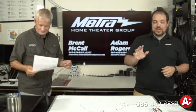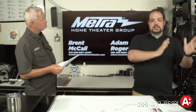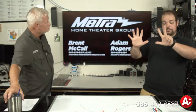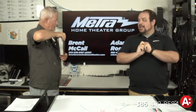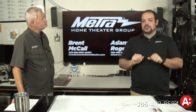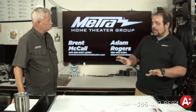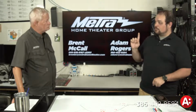With alternative B, what's happening is that it's actually separating out the power and the data. So you have, of course, 8 conductors inside of the category wire or cable. So alternative B will actually separate it out. So pins 1, 2, 3, and 6 now are only data. Pins 4, 5, 7, and 8 are now power.